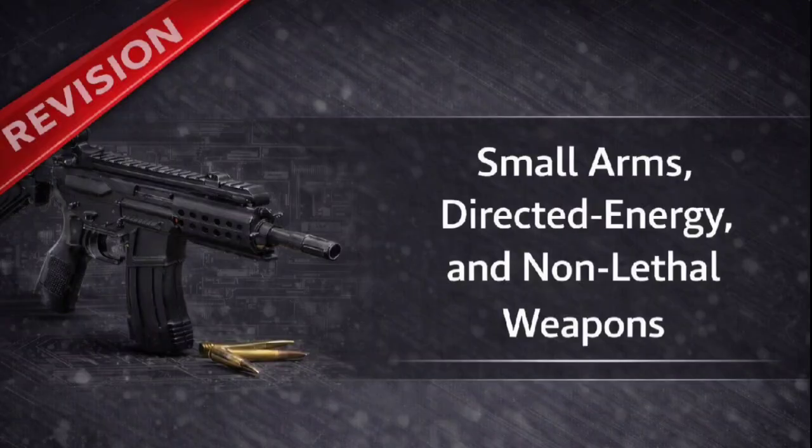This leads to long recoil and short recoil. What are the practical implications of that travel distance? In long recoil, the bolt and barrel travel backward a distance that is greater than the length of the unfired round. So a very long movement. Very long. The bolt is then mechanically held back while the barrel is forced forward first by its own separate spring. This sequence is necessary to reduce stress on the weapon's mounting, but it results in a very slow rate of fire. And I imagine all that barrel movement isn't great for accuracy. It causes significant, unavoidable sighting problems. It's just not suitable for high-precision weapons.